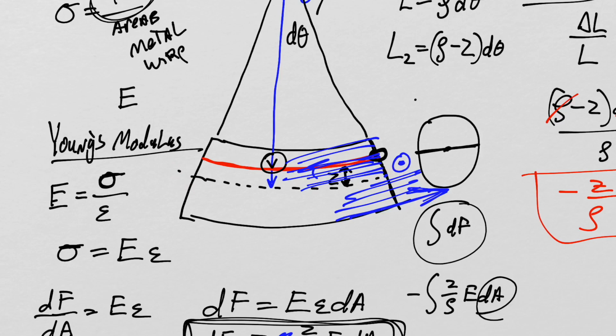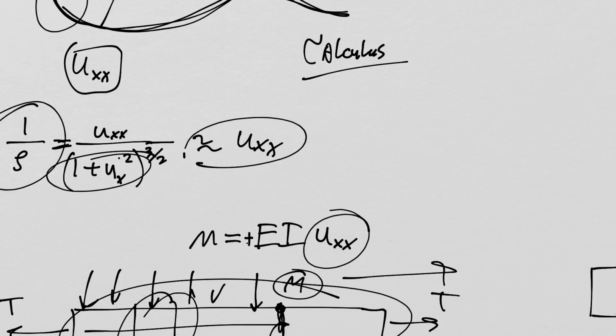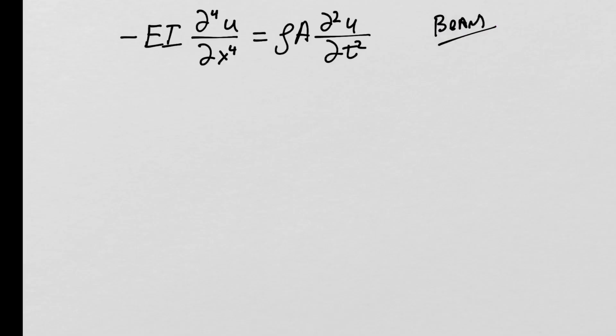And this is effectively longitudinal motion that we consider to be small. That all kind of gets washed away because this angle, this little infinitesimal bit, is infinitesimal. So that motion becomes infinitesimal. So there are a few things there, but the bottom line is this equation is good for a beam, and we need to consider it for a string that has the tension motions.